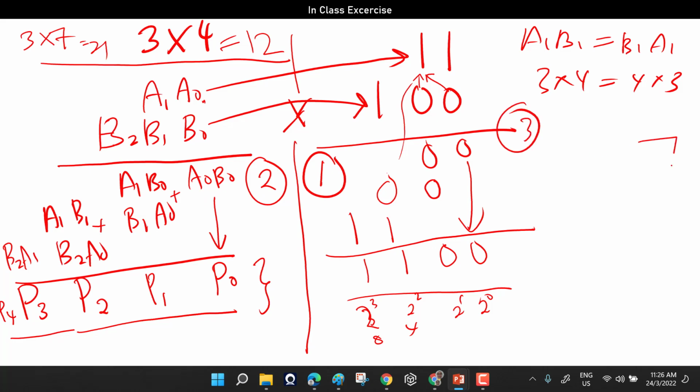So A0, B0, you use an AND gate, that's sufficient. Okay, of course you have here A0, A1, and then here B0, B1, B2. This is the lazy way. If you want notes, you do it properly. The mouse is not accurate, so it's not going to look pretty. Okay, this A0 goes in here. Your B1 coming here. So this will directly become your product 0.